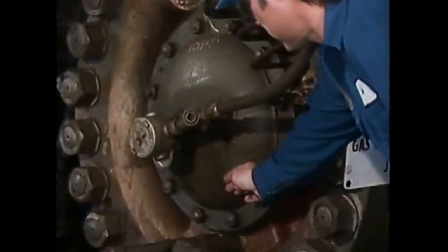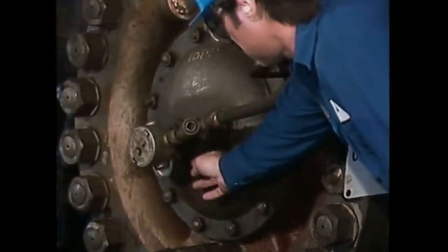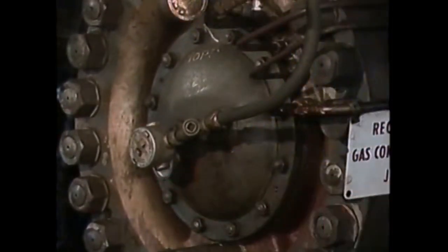It's also important to check the compressor's bearings for excessive vibration and overheating. These symptoms can indicate a possible bearing failure. The corrective action for surging is to increase the gas flow rate through the compressor. This can be done by recycling part of the compressor's discharge back through the compressor, or by routing the gas that's discharged from the compressor to another system for use or disposal.